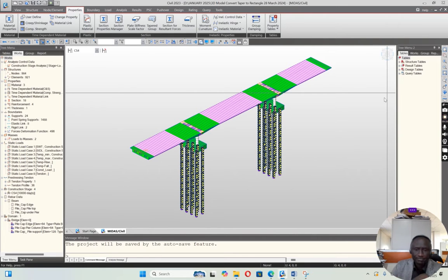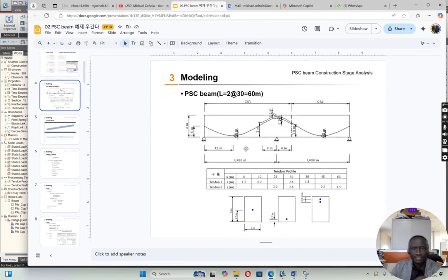This one here is another, related to what I explained the other day. Here you need to understand the tendon layout, the X and Y. It is also very important to calculate the neutral axis of the section, because the tendon locations along the bridge have implications on the performance of the bridge. That will be adjusted until the stresses in service are all within limits.